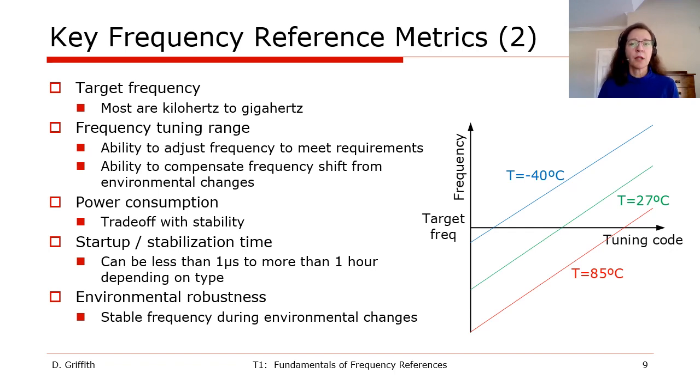Next, the startup and stabilization time are important for duty cycled applications. This can be less than a microsecond for high-frequency oscillators to more than an hour for an OCXO or an atomic clock. Finally, a frequency reference needs to provide a stable frequency even when the surrounding environment changes.